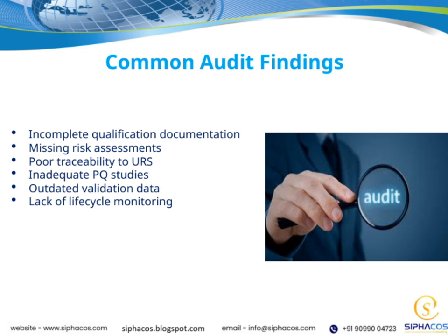Poor traceability to the user requirement specification, or URS, makes it difficult to demonstrate that the final product meets the initial design intent. Inadequate PQ, or performance qualification studies, suggest that our testing may not fully confirm that equipment or processes perform reliably under real-world conditions. Outdated validation data can cause us to rely on information that no longer reflects current operations or standards, which increases risk. Lastly, a lack of lifecycle monitoring means we're not continuously overseeing process performance, which is essential for maintaining quality